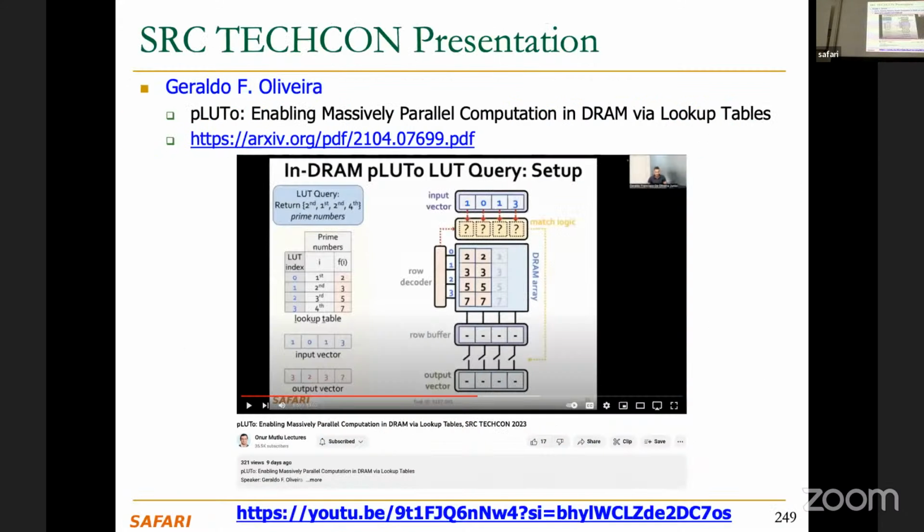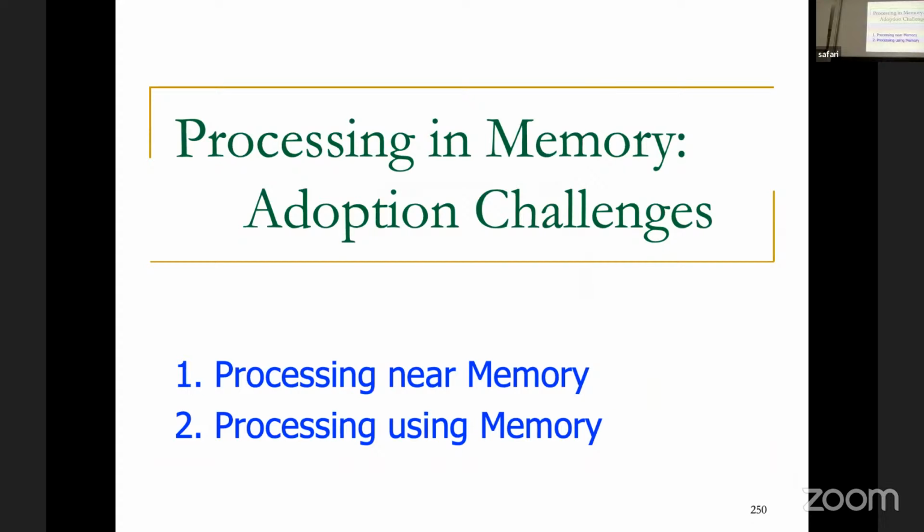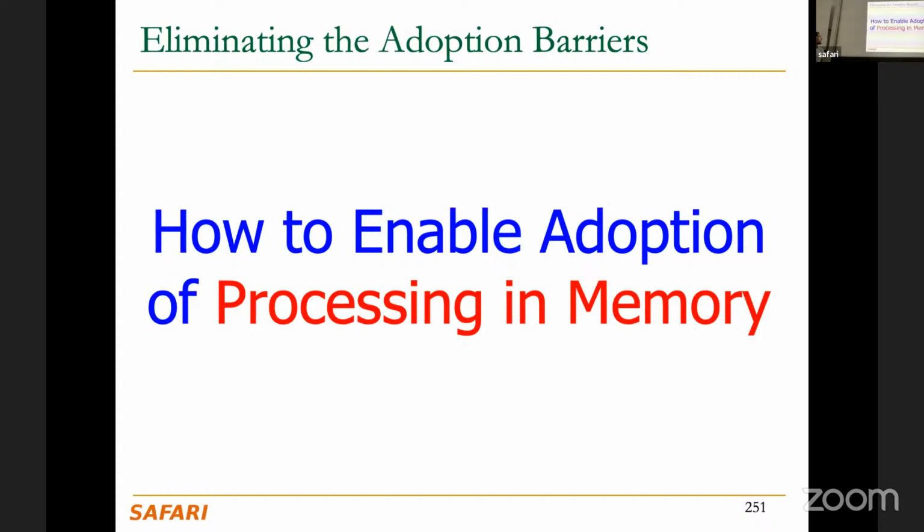And all of that is in this paper. So, as a summary to quickly wrap up, over here I discussed two different types of memory-centric architectures. The first one is processor-near memory architectures, which is adding logic to the memory device to do some computation, and processing-using-memory architectures, which use the analog operating principles of memory cells to perform bulk bitwise Boolean operations, row copy operations, or arithmetic operations.